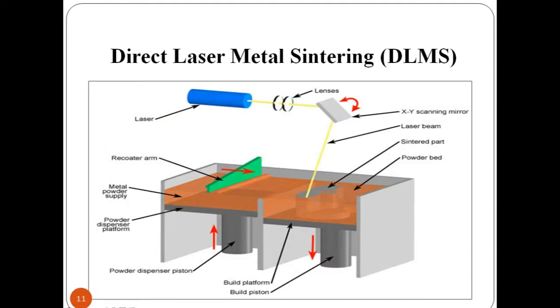DMLS uses a metal powder and SLS typically uses a plastic powder. The powder is spread across the working platform. A laser traces the outline of each part being printed, fusing (DMLS) or melting (SLS) the powder to the layer below it. The platform is lowered, a new layer of material is spread across the platform, and the process is repeated until the print job is complete. DMLS technology has traditionally only been available for printing non-precious metal. Post-printing processing requires cutting off the support material.